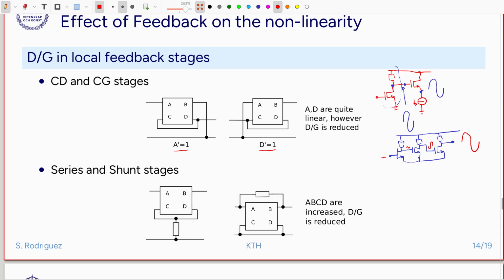And in addition, when we connect this towards the input, there will be much more loop gain than, for instance, in this case, if we do the same and put the feedback here, so we will have much more loop gain in the case down. We will have other problems here, of course. There will be stability issues that we have to solve, but we will deal with those in a different lecture.